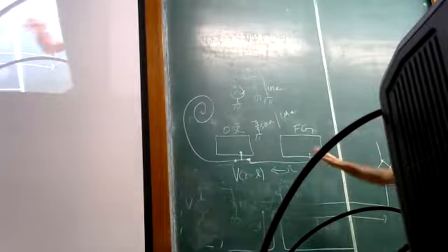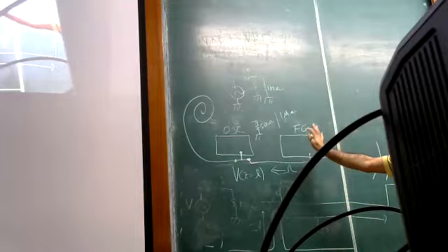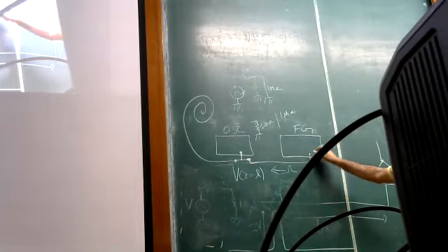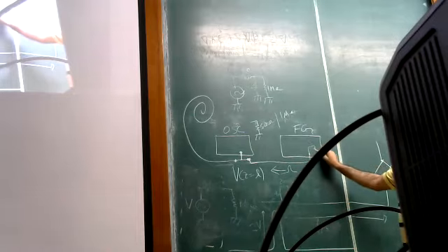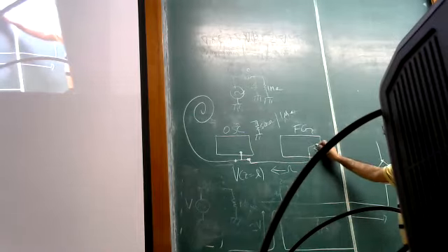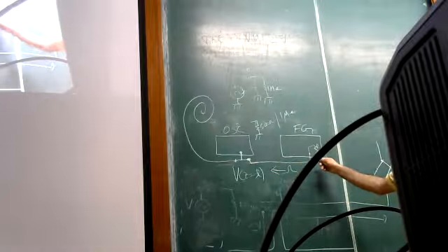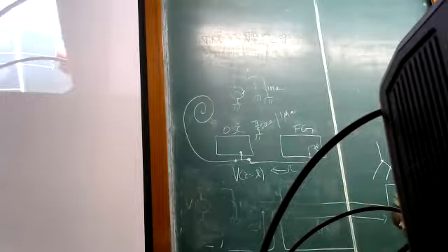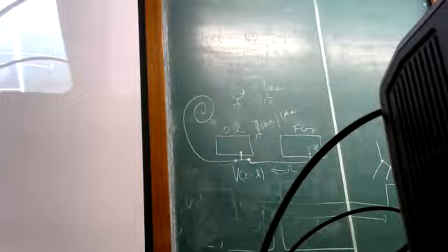Remember I said that the function generator is always a 50 ohm source in this case. Even if I set the output load, it just changes the display. The source here is always 50 ohms. So this is matched. So that pulse, once it reaches here, will no longer reflect. So the cycle ends. There's only one set of things going on.